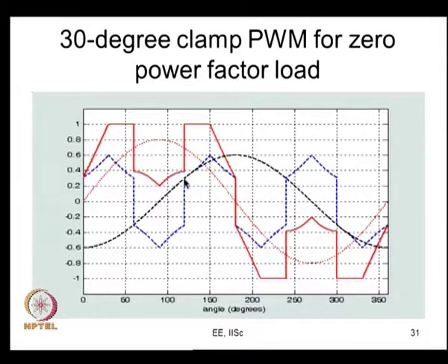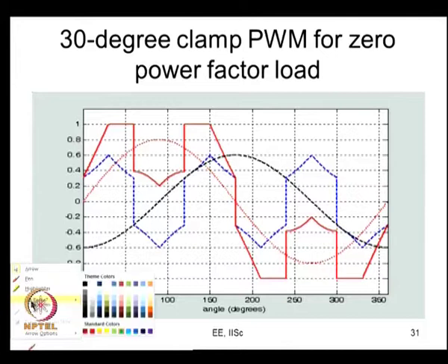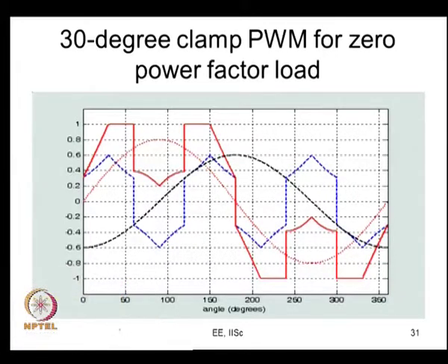It is fine. You cannot clamp it when it is close to its peak, because the voltage is close to 0. So, you are doing the best thing, you are clamping this phase when the current is between 0.5 times the peak to 0.866 times the peak. Let me draw this energy loss. So, if I draw the energy loss, here it follows the current up to what point? Up to this point, then it is 0, then up to here it is 0,